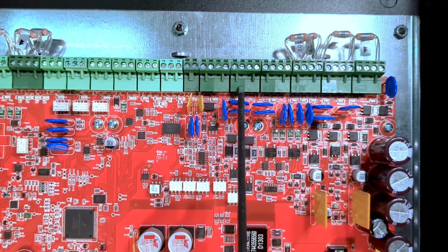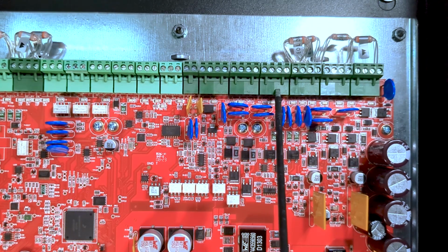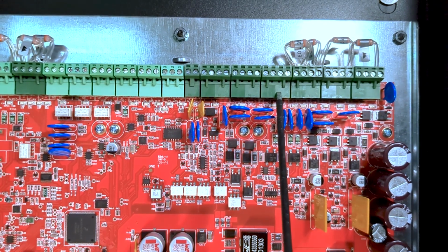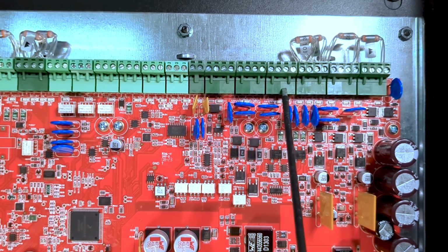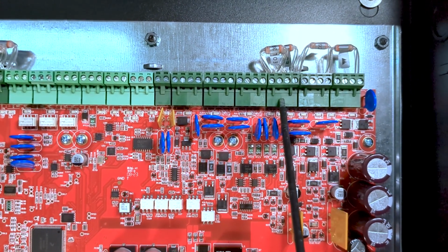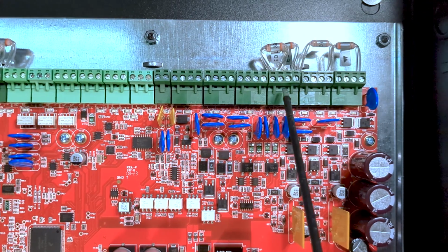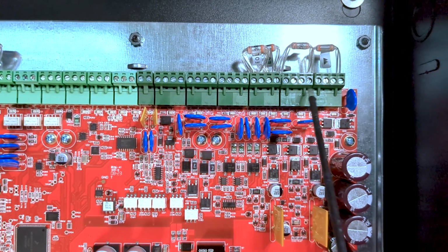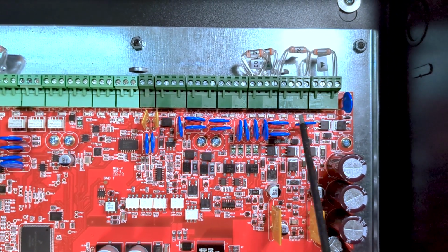To the right, we have 2 sync input that passes synchronization from NACs circuits, which can also be used to activate zones. The sync output connects to subsequent booster panels to pass along the synchronization. Next, we have 2 regulated 2.5 amp NAC circuits to drive horns and strobes.